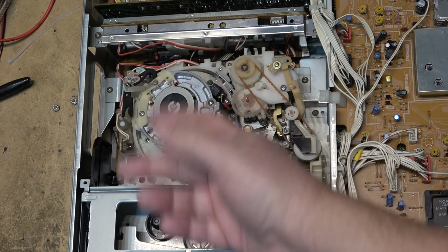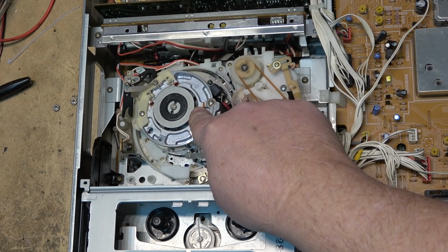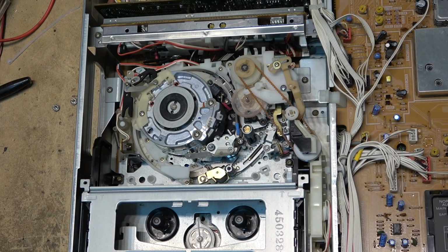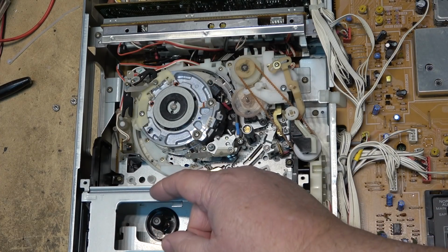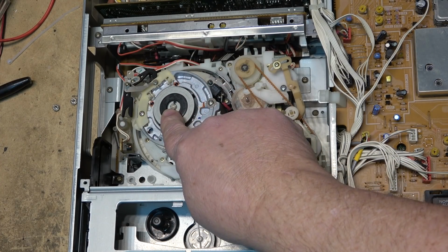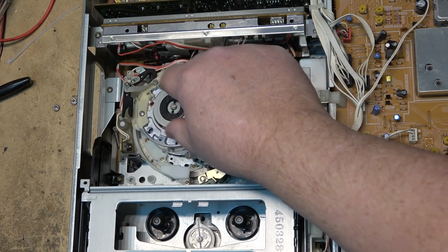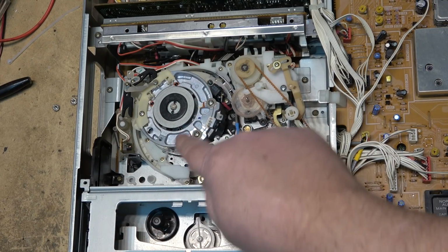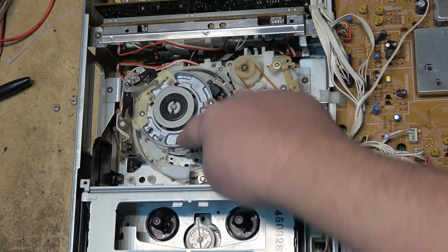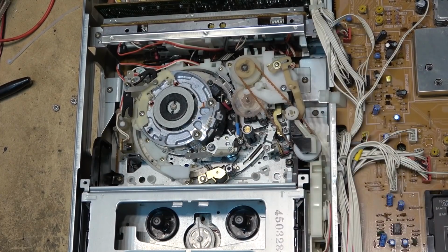And I've still got the good head disc. If the heads wear out on the drum, I'll transplant the head, because the rotary transformer for the flying erase heads was actually on top, and the rotary transformer for the video heads was below the drum. So I keep my old SLHF1000 head drum just for the day that the heads wear out and I need to change them again, because parts for these things, of course, is very hard to come by.